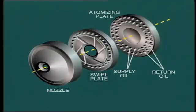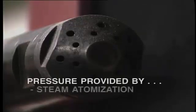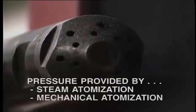A swirl plate is also fitted at the tip just ahead of the nozzle so as to impart a twisting motion to the fuel spray as it enters the furnace. Two methods are used to provide the pressure necessary to force the oil through the burner tip. These are known as steam atomization and oil pressure atomization, known as mechanical atomization.